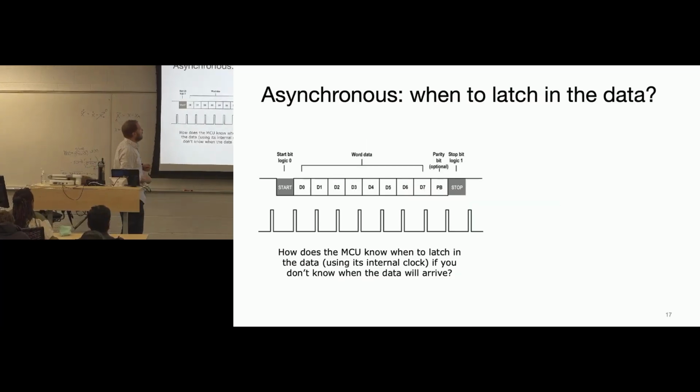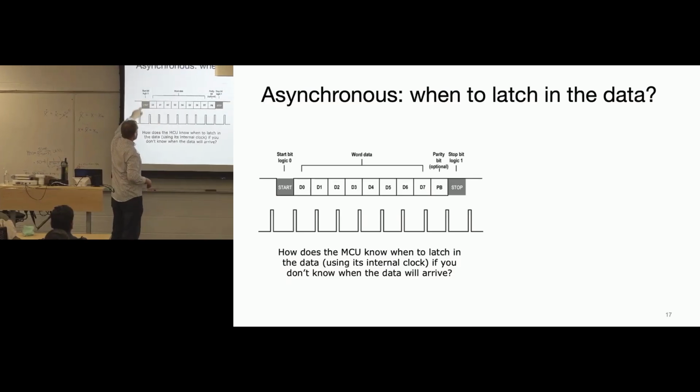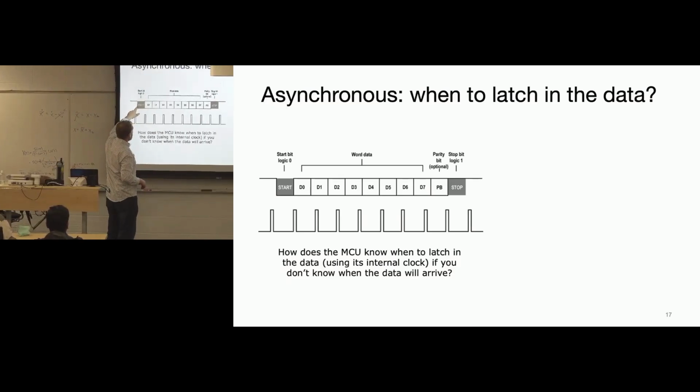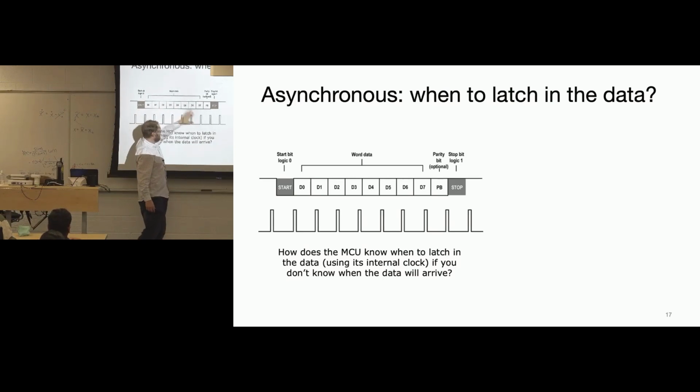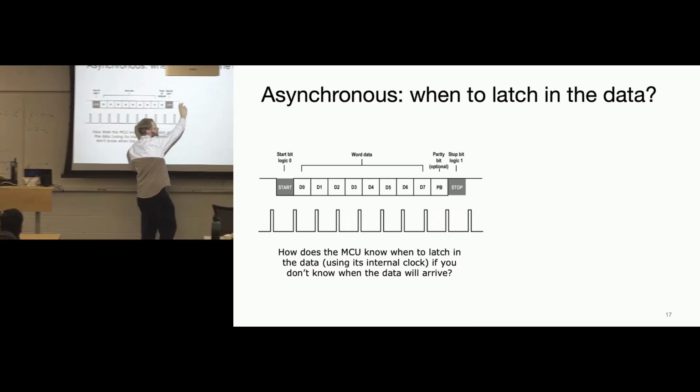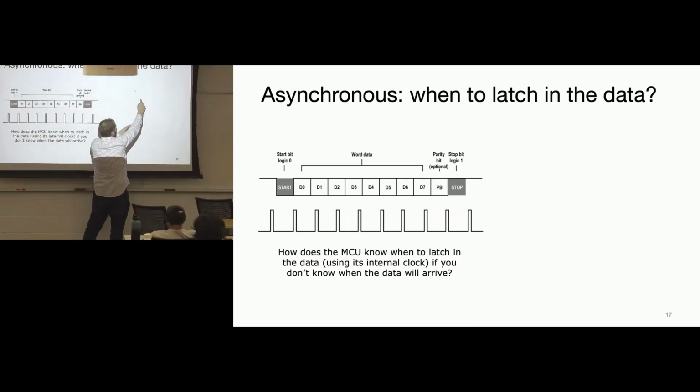All right, so going back to synchronization, how do you actually do this? We said we're going to use a starting edge to denote when we're supposed to clock in. What could you imagine could be a challenge with this? Well, I'll just tell you. If this clock is not perfectly synchronized to this clock, eventually they're going to get out of sync. Say this one is 5% faster. Well, eventually, over here, they're going to become out of sync.